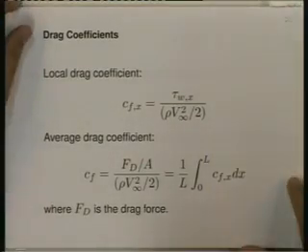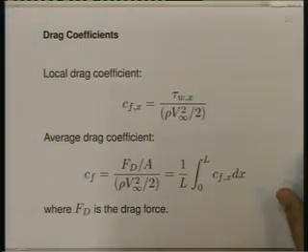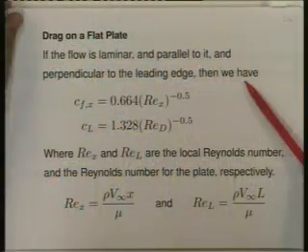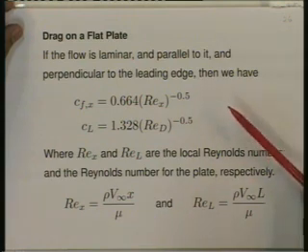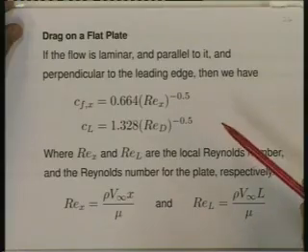The flat plate situation, which we have been mentioning again and again, is a basic or fundamental flow situation. The governing Navier-Stokes equations in their boundary layer form can, with some difficulty, be solved for this situation. If the flow is laminar, steady, two-dimensional, constant property, incompressible, then we can analytically obtain an expression for the local drag coefficient and the average drag coefficient.